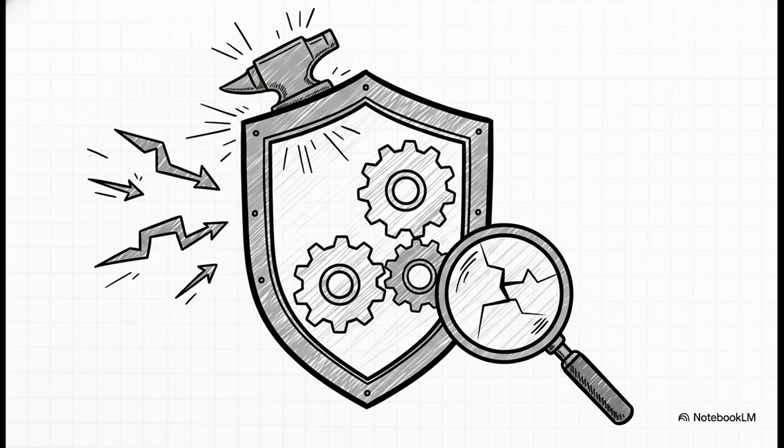Now this next concept might just be the absolute climax of this entire explainer. Listen, the real world is completely ruled by uncertainty. You can perfectly execute that 8-step flowchart on paper, and your math can be totally flawless. But when you physically go to build the machine, there are always going to be variations in the physical dimensions, there will be microscopic non-uniformities in the material's strength, there might even be an unexpected sudden impact load.